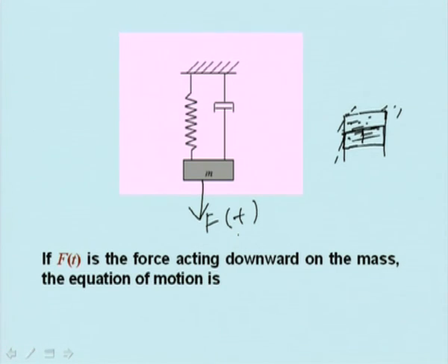Actually, you will not always observe a dashpot in a system, but we are only modeling. We will see that the same type of effect which this dashpot provides may be provided by some other mechanism. Like if a cantilever beam is vibrating, many particles have that influence. So this is very complicated, but we can actually model it like this.